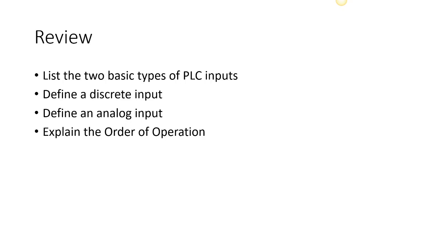And then we're going to write that to some output. Every rung has to have an output, and an output instruction is what is going to write to an output table. I can't say it's the only way to write to the output table, but inside the PLC, it's the only way to write to the output table. There's other ways with computer programming outside of PLCs to be able to do that, but that's beyond the scope of what we're doing. Okay, so we are going to write to our output table from our program execution, but we're not writing to the output channel, just the table.